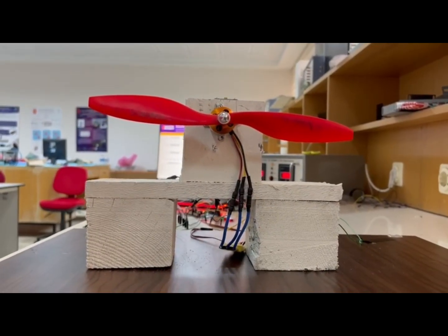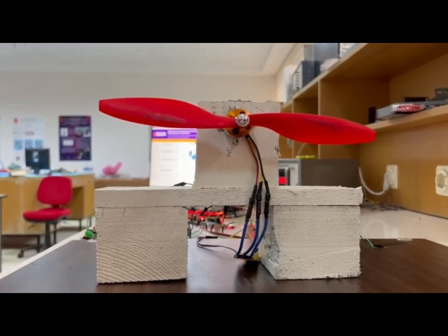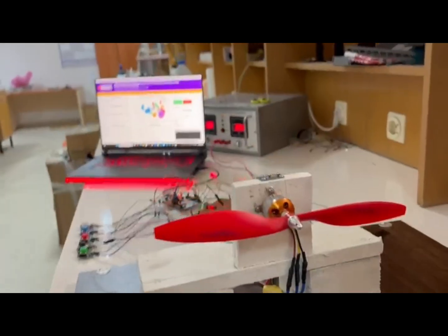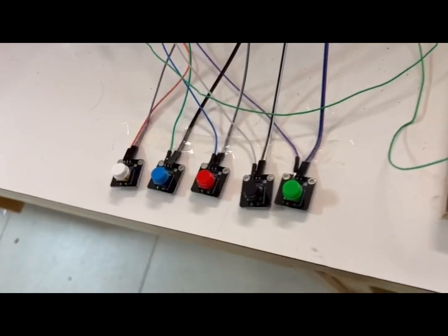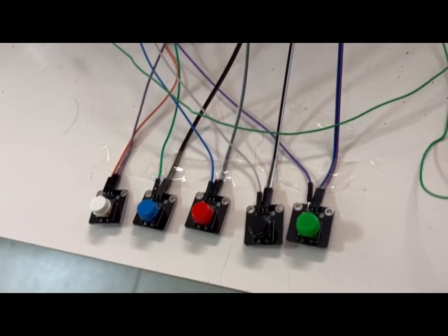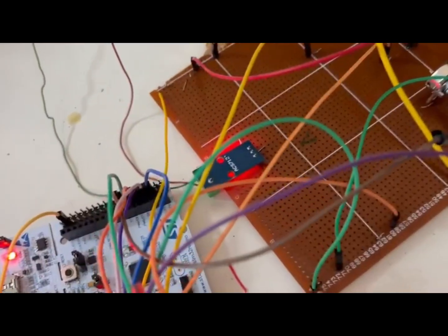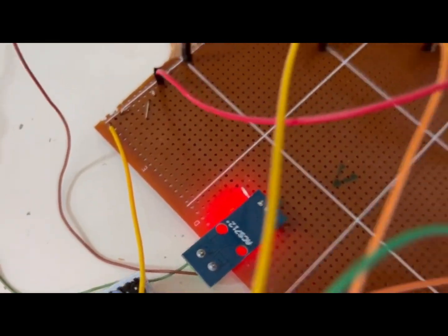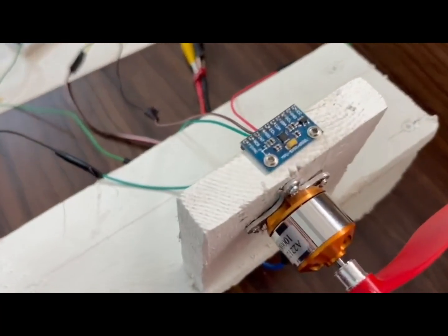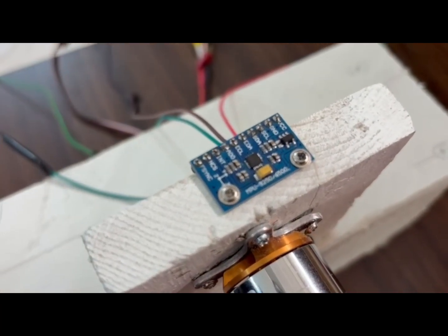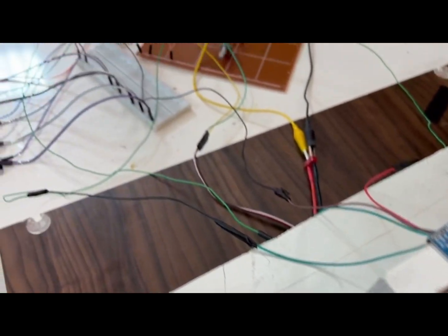In this project, we developed a bare metal embedded system for brushless DC motor control and real-time data acquisition. The motor speed is controlled using 5 external buttons, where each button corresponds to a predefined speed level. The system uses two sensors, a current sensor and an accelerometer. Both sensors operate at a sampling rate of 500 Hz, and the internal filtering features provided by the sensor modules are utilized to improve signal stability and measurement accuracy.